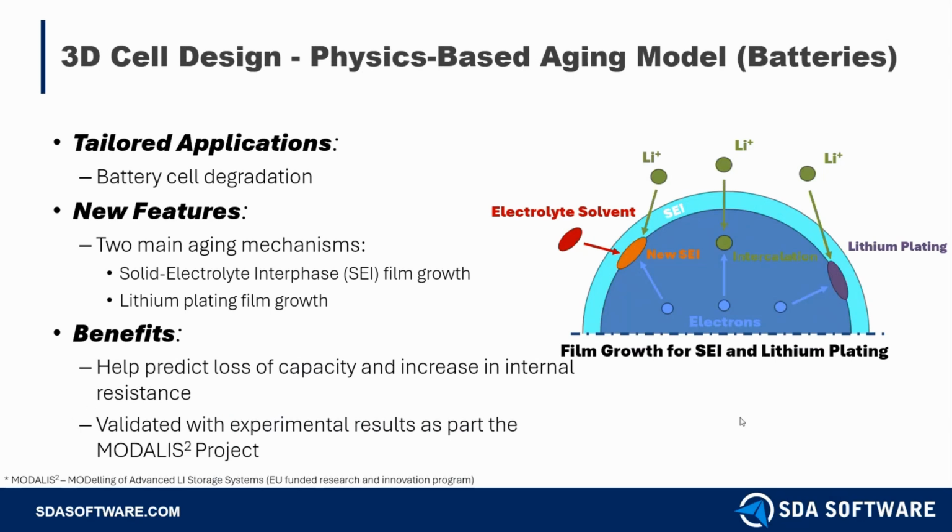Besides the new multiphase modeling capabilities, STAR is introducing new physics-based aging models for battery designs. The new model can help battery designers predict battery cell degradation and improve battery life cycle. There are two main aging mechanisms STAR has introduced in this version: the solid electrolyte interface (SEI) film growth and the lithium plating film growth.